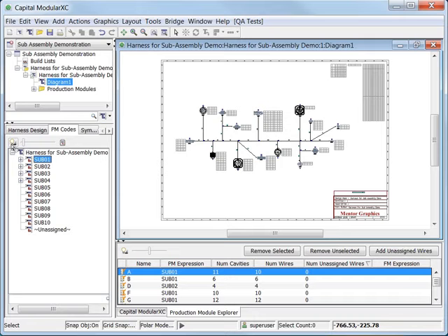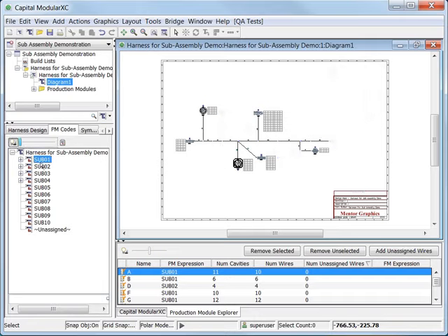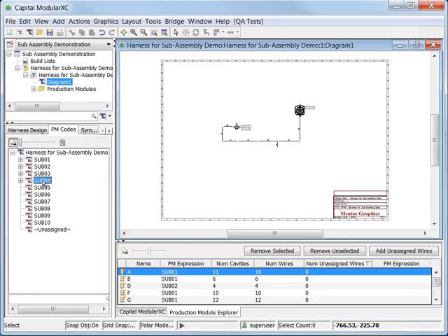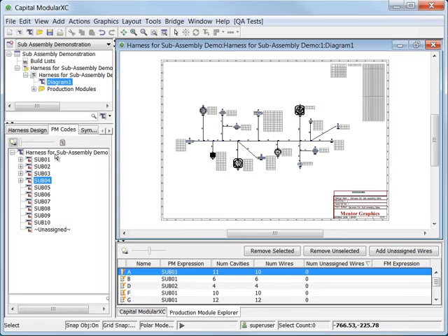My modules are complete. Turn on the dimmer so we can get a bit of a preview. So sub 01 is going to look like that. Sub 02, 3 and 4. So at this stage my interactive assignation is complete. And as mentioned, the large proportion of that work could have been automated via the plugin, and then it could be down to me as the experienced user to finish off the components where the plugin failed to assign, or analyze the smaller assemblies and choose to merge them into bigger ones that would be better suited to balancing my production, or split out some of the large ones to make smaller assemblies for the same reason. Either way, with the interactive tools I can finish off my assignation to get me to a condition that you can see here.